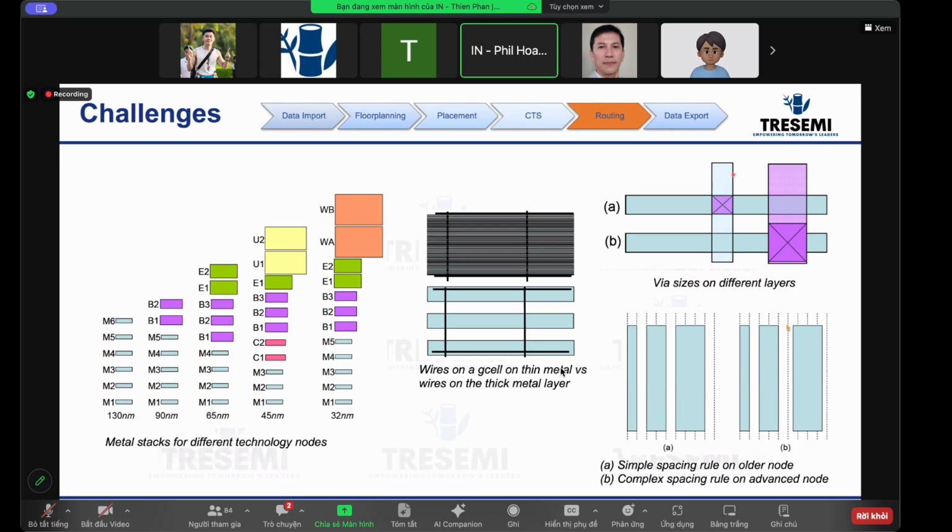That's why you see these thicker wires, and then many of them added just to be able to route within a small area. Yeah, that's why shrinking geometries increase the number of layers and also increase RC delays with respect to transistor delays.